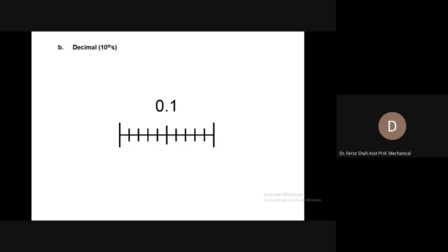So for this, you will use the hit and trial method. Now, what is the hit and trial method? This be the center, open the compass to a convenient length so that you understand that you want to divide it into five equal divisions. For example, you have opened your compass to this much length.